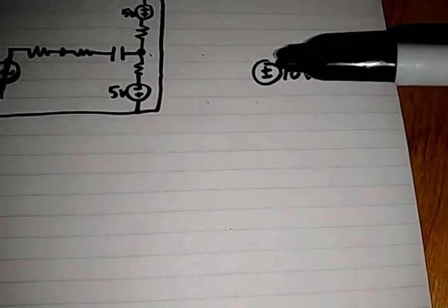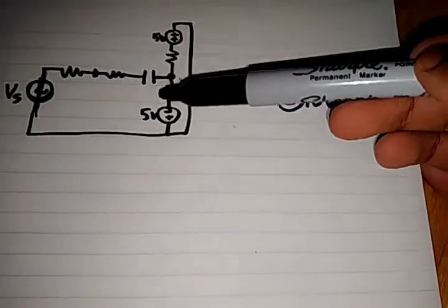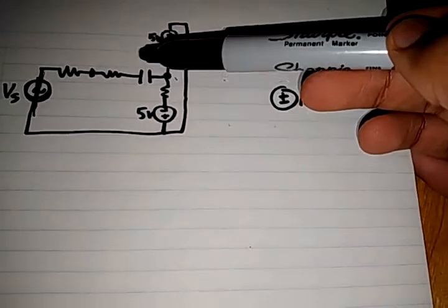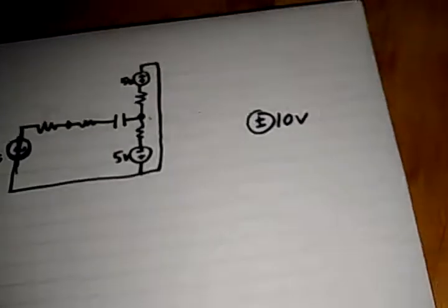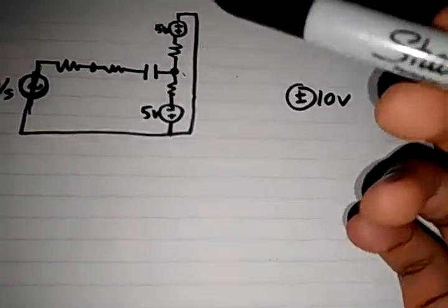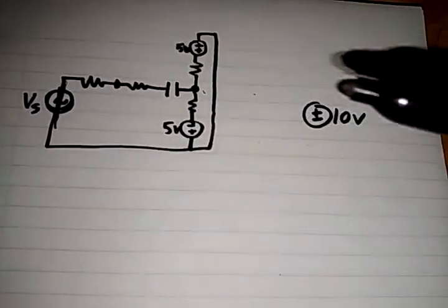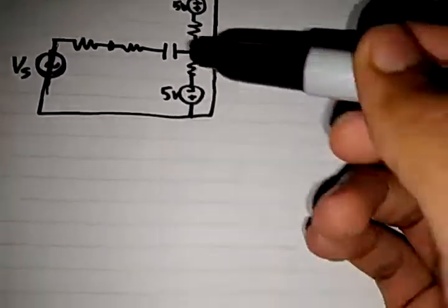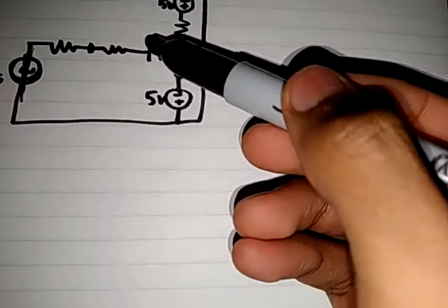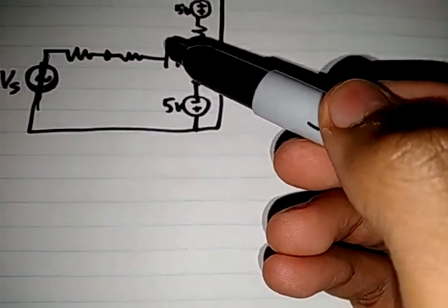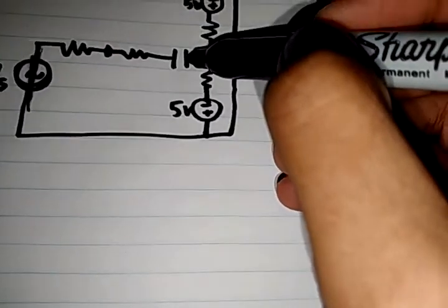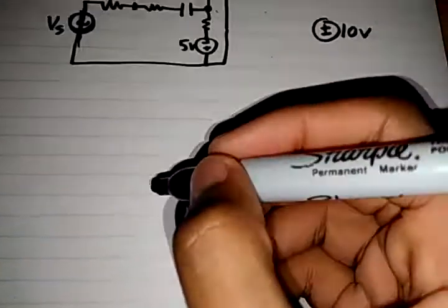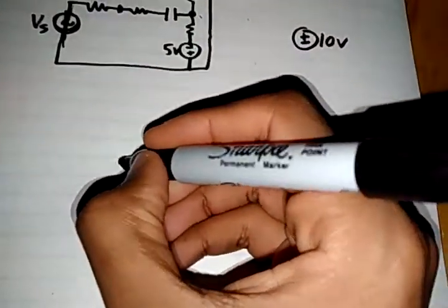And also what's very important is that notice that a capacitor is short-circuit to DC. A capacitor is short-circuit to DC, and open circuit to high frequency AC. Whereas if you can remember, an inductor would be the opposite. But in this case, capacitor, so this is open circuit, which means even though I short-circuited this, this part is an open circuit. Which means if I redraw the circuit, it's going to be something like this.